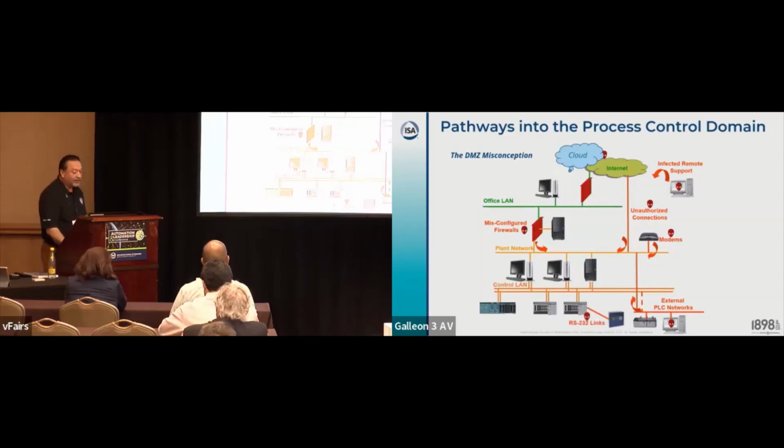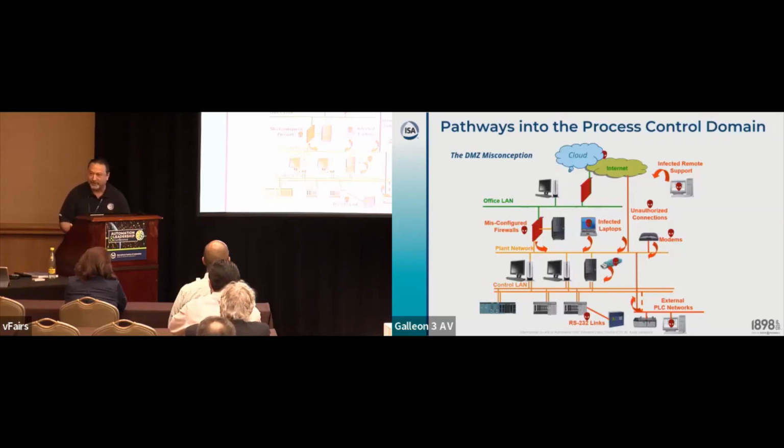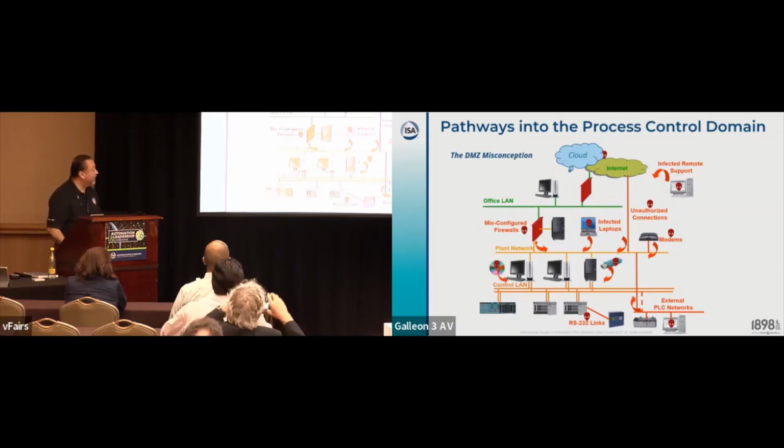So where am I going with this is that we have a lot of pieces to it. We've got infected laptops. It can happen: downloading a driver, trying to do your job in the middle of the night, can't communicate with a certain PLC, going to the internet, pulling in some malware by accident, and now infecting your system. So we have to be very aware of that.